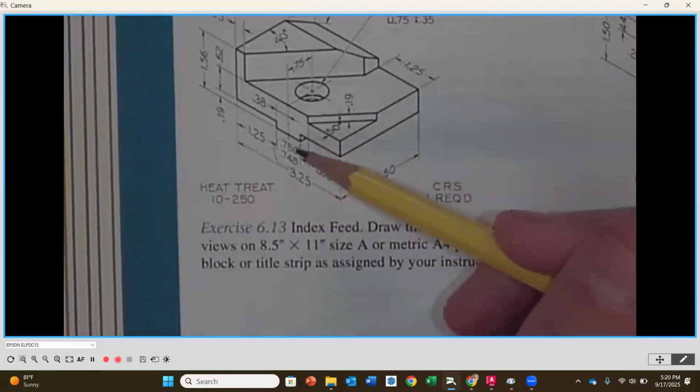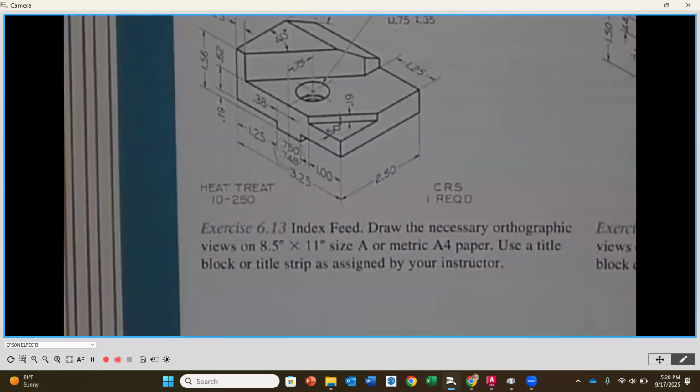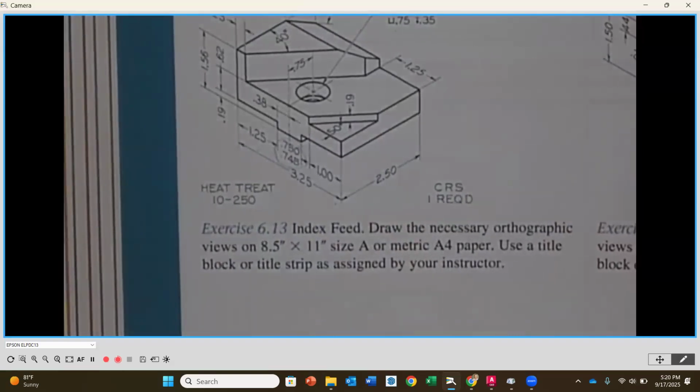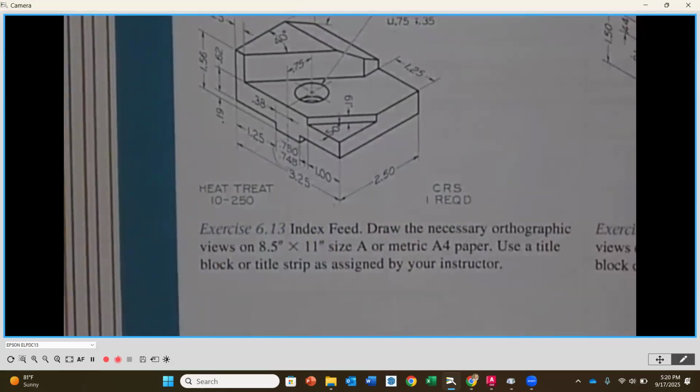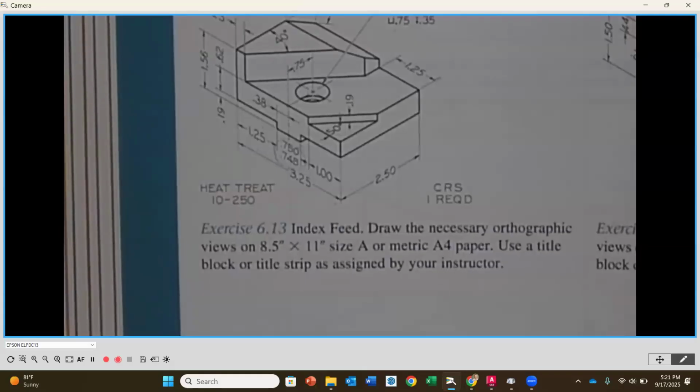If the limits, one of the high or the low, wasn't a value that was in there. So let's say this came out and they had 0.756, okay? And then the bottom number was 0.748. Because 0.75 would have been in that range, you still draw it to 0.75. Does that make sense to everybody? So you look for that nominal, like in this case, inch increment. If it was for a millimeter, then you would look for that nominal millimeter value, and then you draw it to that.